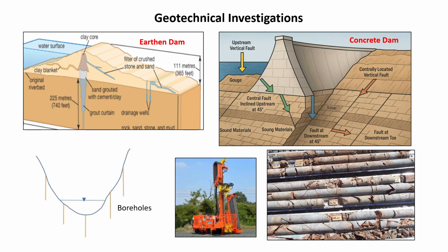So we must know the foundation where we are getting good rock, disturbed rock or weathered rock. This can be known by doing some boreholes at the dam site. As shown in the left bottom image, for any river cross-section, we will plan some more boreholes preferably at the center, and on the abutments. The machine for boreholes will look like this.